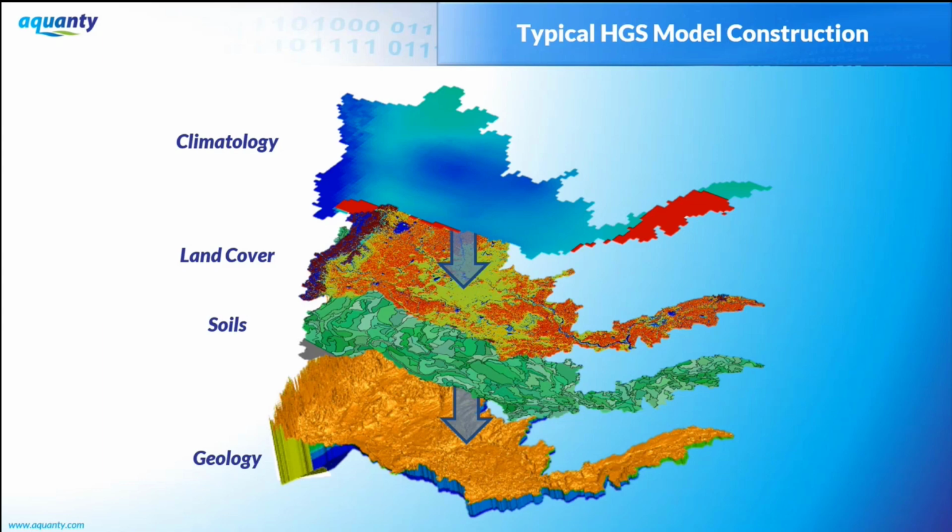Much of this is available. And then there's the subsurface geology or hydrostratigraphy, which controls the deeper groundwater flow. What we found, at least in Canada, and I think it's probably true in other countries such as the US and some European countries, is that these data sets are publicly available for the most part, and certainly to a degree sufficient to build a plausible integrated hydrologic model.